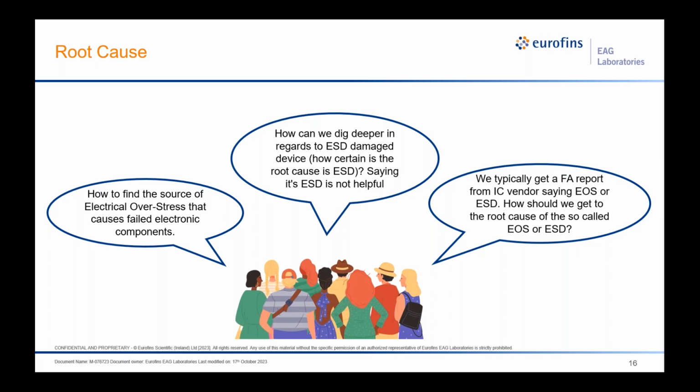Yeah, so ESD is generally a more subtle amount of damage than an EOS event. There are also different things about EOS and ESD. ESD depends on the source being limited, right? Because it's just the initial strike based on the capacitance of whatever it was discharging into or out of your device. The ESD damage may be even overshadowed by subsequent biasing, so that makes it even more complicated to reverse engineer.